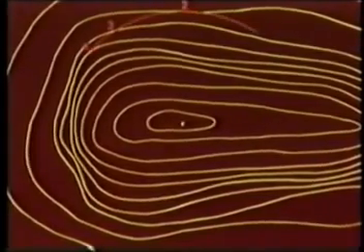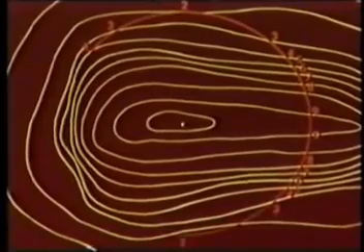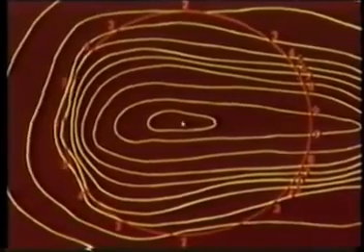It is often more useful to know the shape of the field radiated by the antenna. To achieve this, we obtain field strengths at a fixed radius from the antenna. We now use a vectorial presentation to give each reading a magnitude and direction.